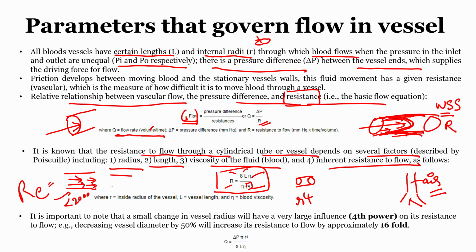And if the fluid flow is turbulent, that is the direction of the fluid flow cannot be controlled through a channel due to various reasons, and why the flow becomes laminar or there is a transition from laminar to turbulence, we will see in the coming slides. So, when there is turbulence, the Reynolds number is greater than 4000. Anything between 2000 and 4000 is called the transition.